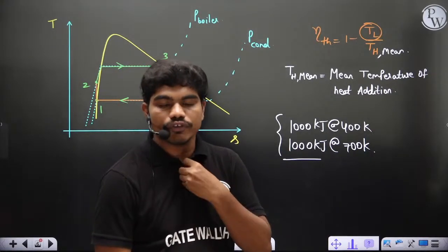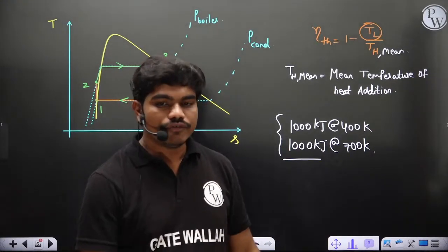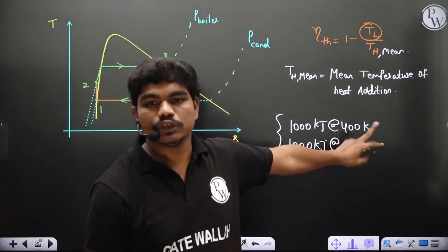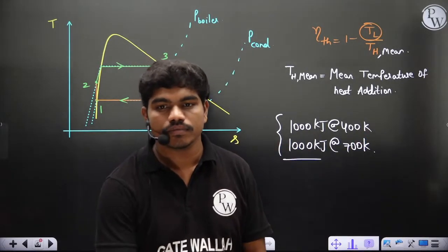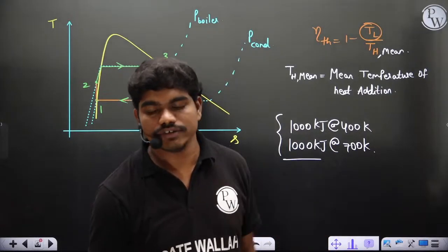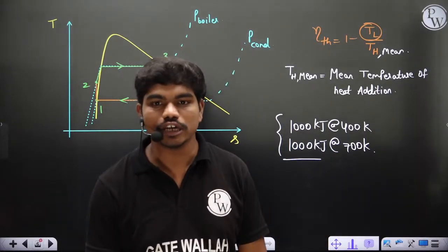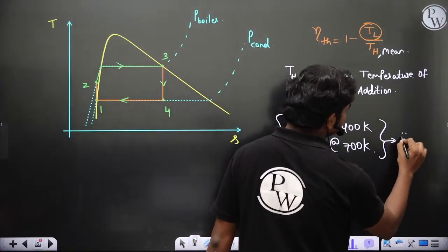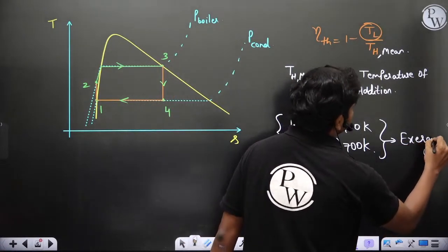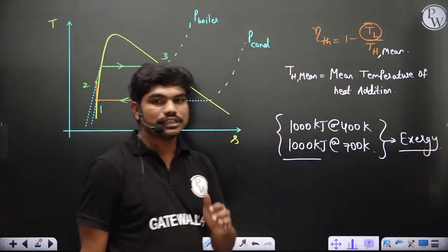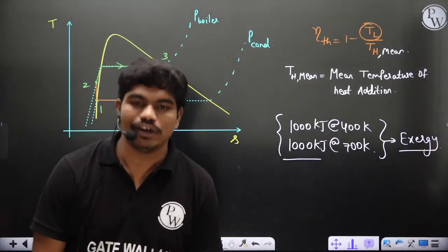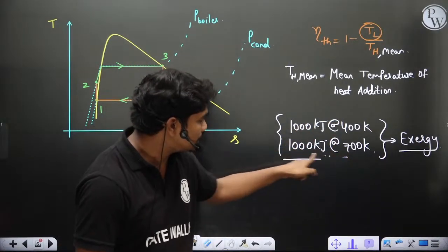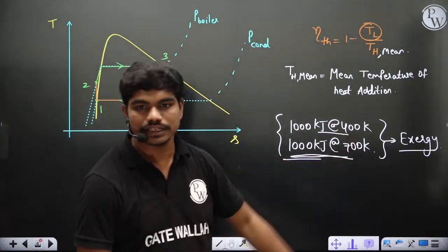From the second law of thermodynamics point of view, if you see these two amounts of heat, do these two have the same capacity to generate work? No, correct? Because we defined something called exergy, one easy chapter again, which depends on the sinks, correct? So therefore, high temperature has high quality. Yes, of course, we can understand. We'll say it has high exergy. So this is more powerful than this, is what we know actually.